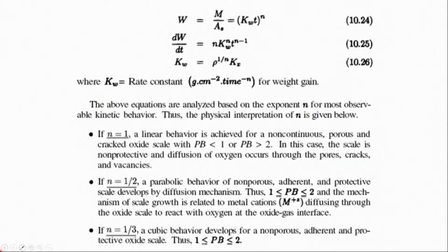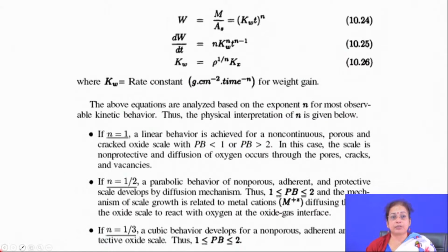Here the kinetics of the scale growth is very slow, and it shows parabolic behavior. In this case the diffusion of the element, or counter ionic diffusion, is responsible for the film growth, but the rate of film growth is quite slow. The way the film will grow depends on the relative diffusivity of the individual element through the scale.